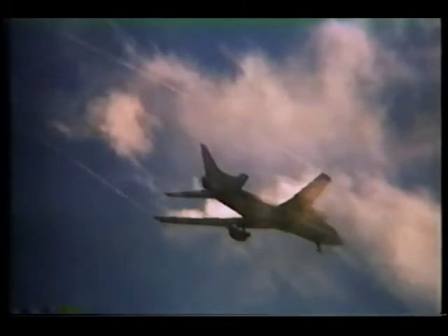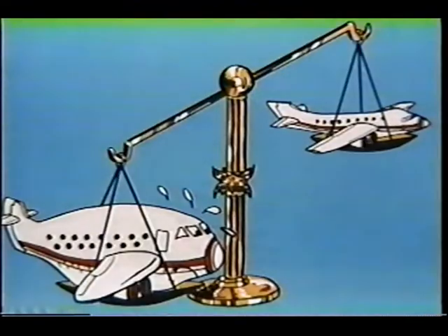Take this heavy jet, for example. In a few minutes, it's going to land at its maximum certificated landing weight. By that, let's say that we're talking about 350 passengers, lots of baggage, and tons of fuel. Now imagine that same heavy coming in from a ferry flight and landing with no passengers, no baggage, and only 1 hour of reserve fuel. It doesn't take a lot of figuring to realize that the airplane in the second example could weigh 100 tons less than the max weight airplane, and that there will be a significant difference in VREF speeds between the two.